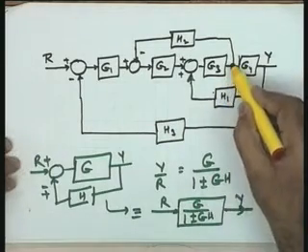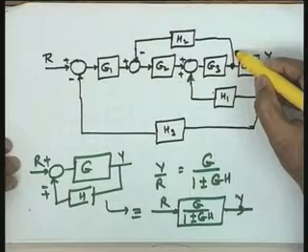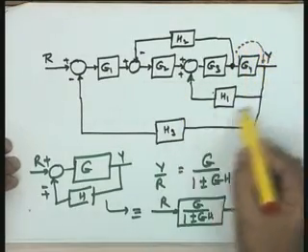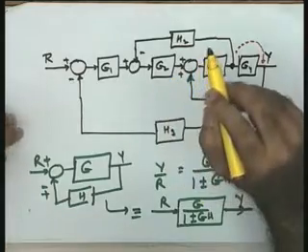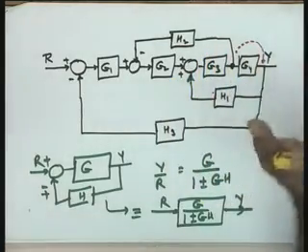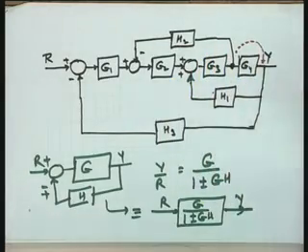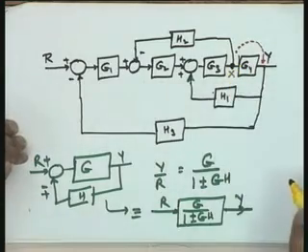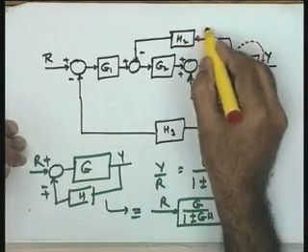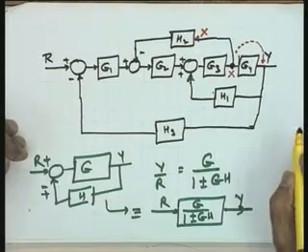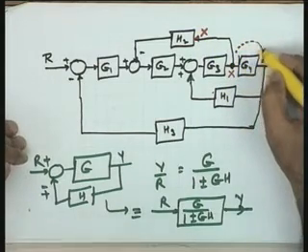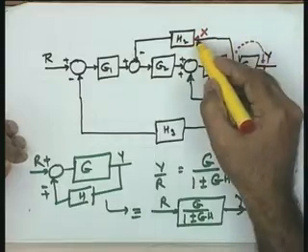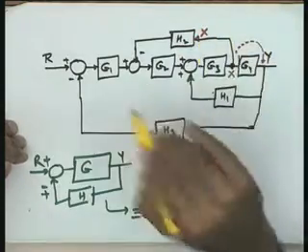So, if I pick up from here, if somehow I am able to transfer it to this point, in that particular case you find that a basic feedback loop results. Okay? You see that the block diagram is a representation of system equations. If I name this variable as x, it means the input to this particular block is x. There is absolutely no problem if I shift it here, provided you can assure that the input to this particular block will continue to be x.